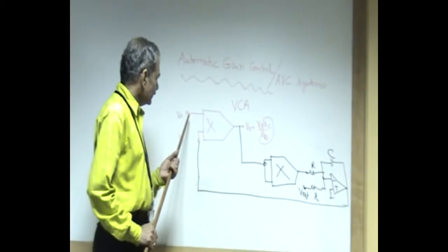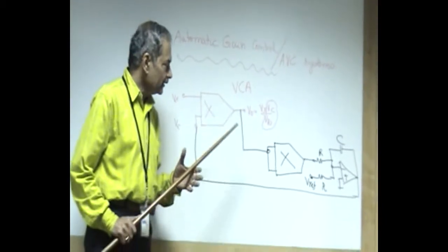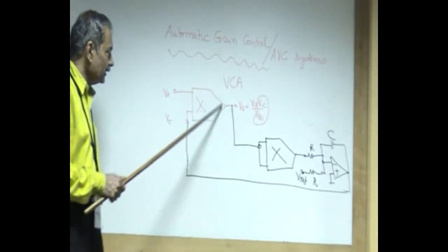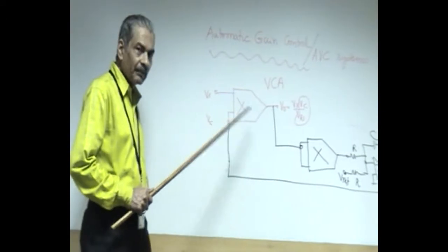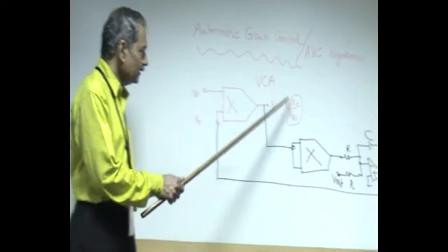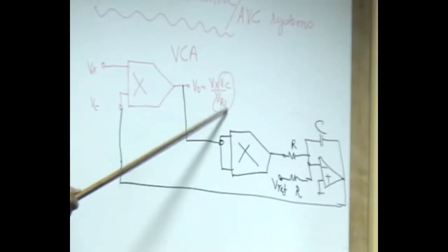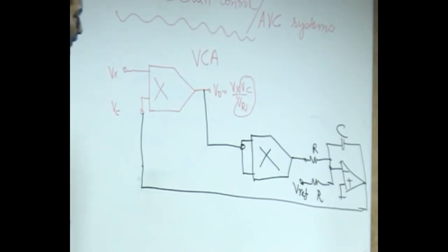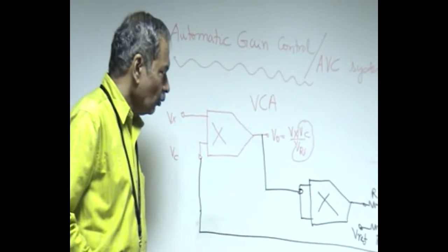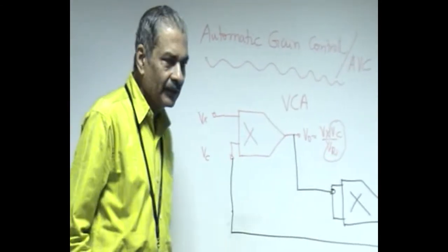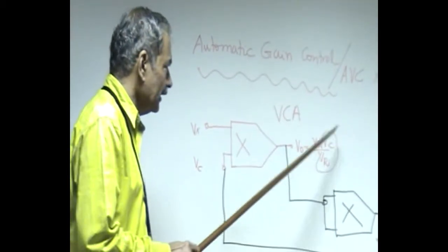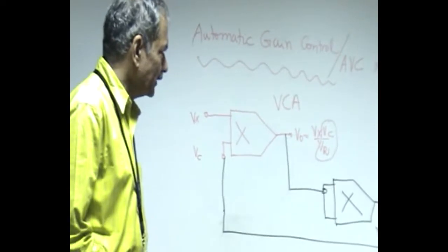So let us now establish a voltage controlled amplifier, and the voltage controlled amplifier is nothing but a multiplier. An ideal multiplier is being used, Vx into Vy, which is Vc, control voltage, X into Vy divided by Vr, where Vr is the constant of proportionality of the multiplier. So such precision multipliers with a standardized value of Vr of about 10 volts exist, which can handle signal of the order of plus minus 10 volts.